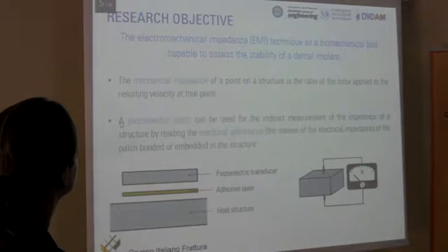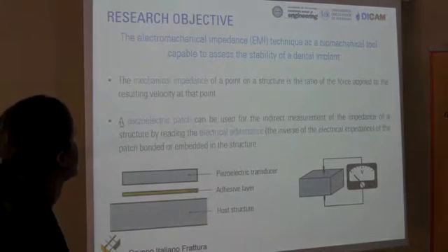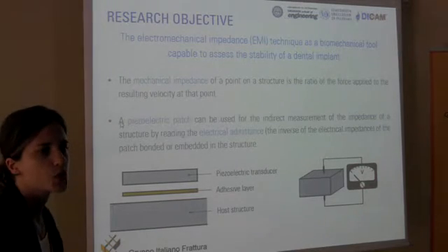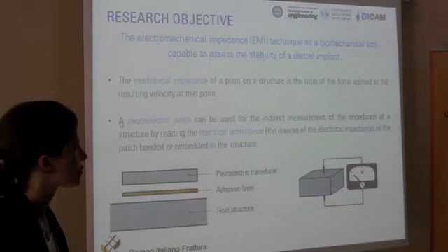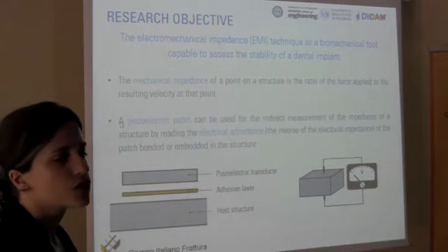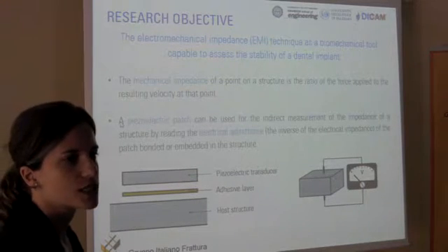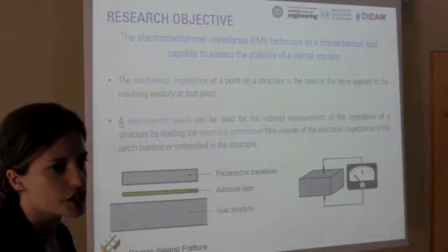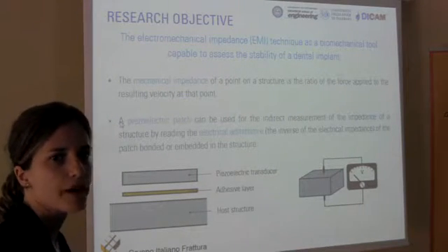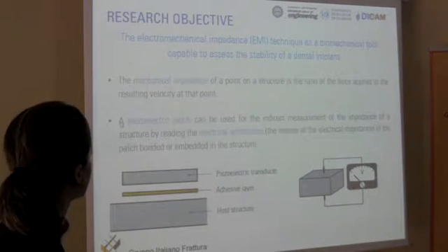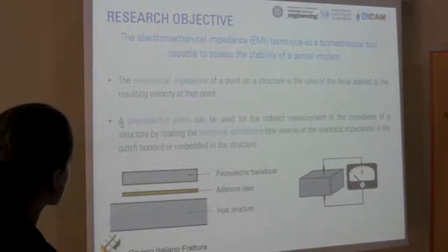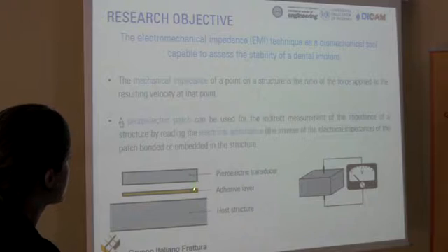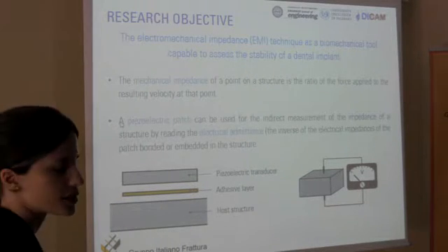So let's move on to our goal, that is to apply the electromechanical impedance technique to assess the degree of osseointegration. Actually, this method is generally used in the structural health monitoring of aerospace and mechanical engineering, and its application in biomechanical engineering is rare. The method consists of bonding one piezoelectric transducer to a host structure to be monitored.